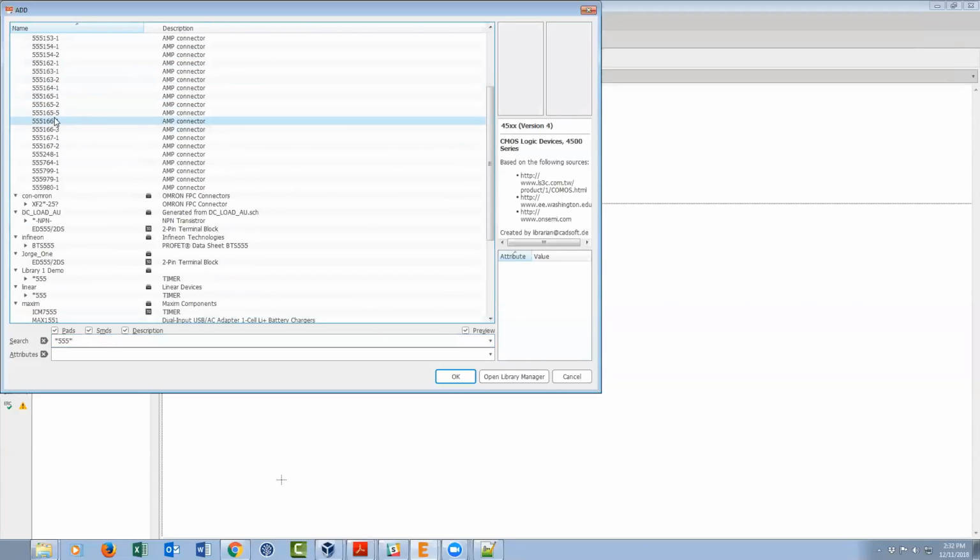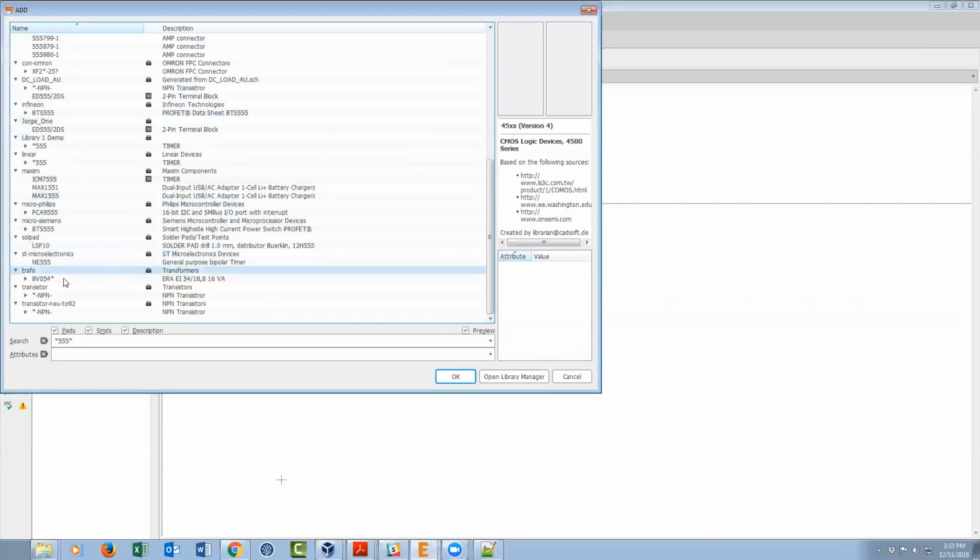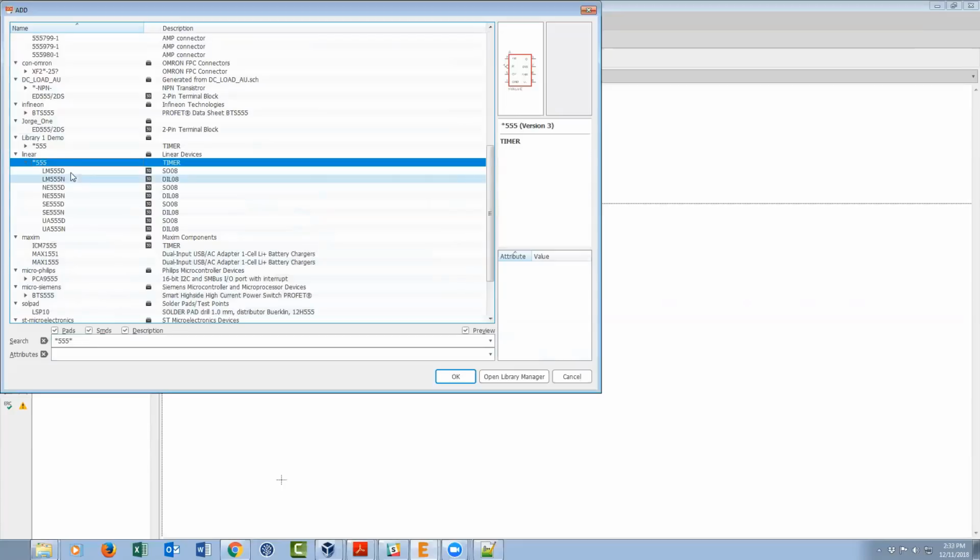And you can see now we get a whole bunch of stuff. And again, not all of it applies. So that's how you do the searches in Eagle, from least flexible, where you don't have any wildcards, to most flexible, which would generally involve multiple asterisks in your search string. So with that, let's go ahead and bring in the part that we want to use.